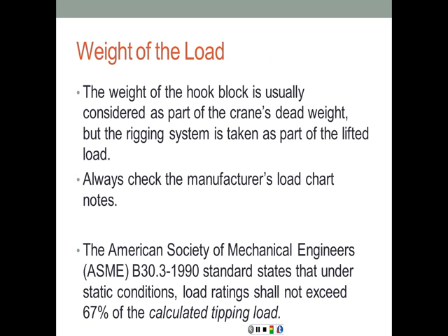Always check the manufacturer's load chart notes, and the American Society of Mechanical Engineers standard states that under static conditions, load ratings shall not exceed 67% of the calculated tipping load, because you're going to have some wind loads, some motion of the load itself, which is going to create a dynamic load on the boom of the crane, which is going to lessen the total maximum allowed load at the end of the boom.